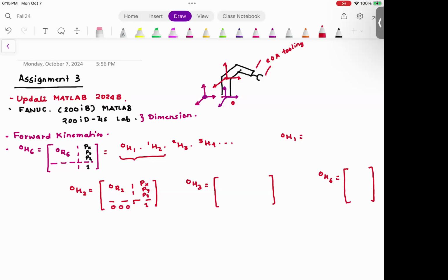With the measurements, you need to find out if the robot coordinate system is at the same location where you assume your coordinate system is. Second thing, the X, Y, and Z of the coordinate system are aligned with the X, Y, and Z that we have assumed. Otherwise, at every step, you will see the answers would be positive or negative. Don't worry about it. Just add the terms corrected, add positive or negative signs.